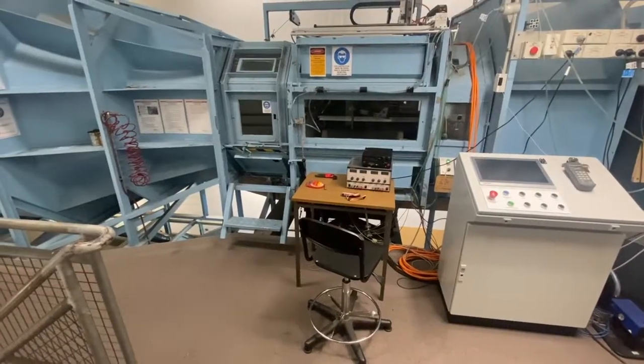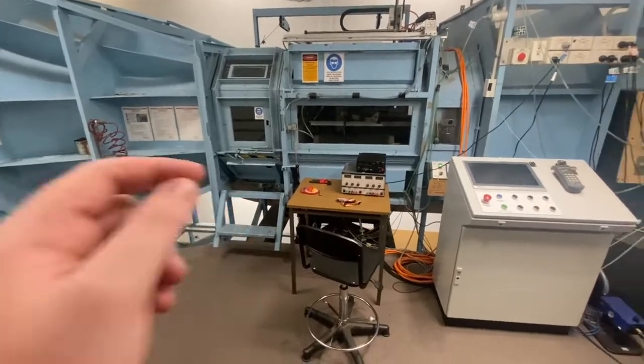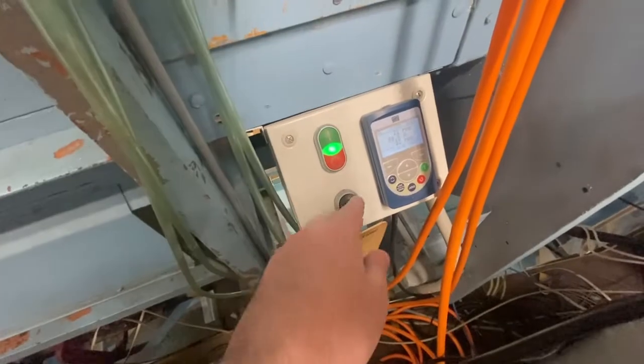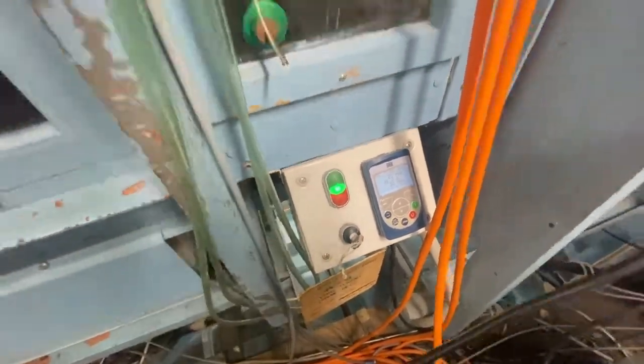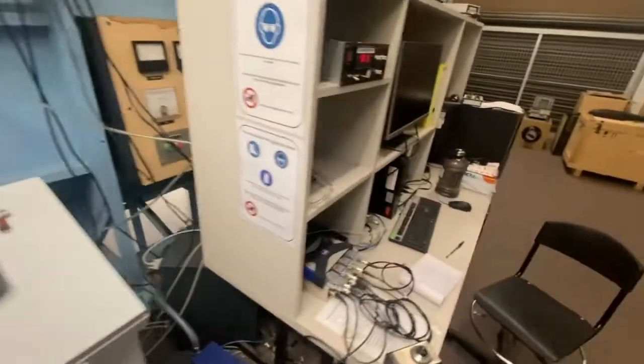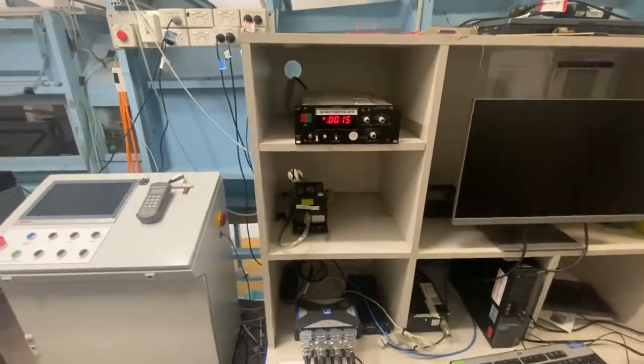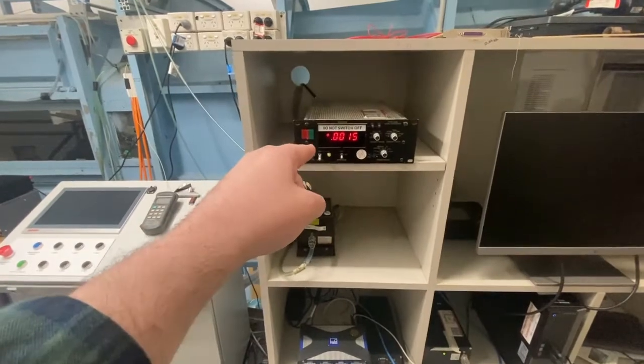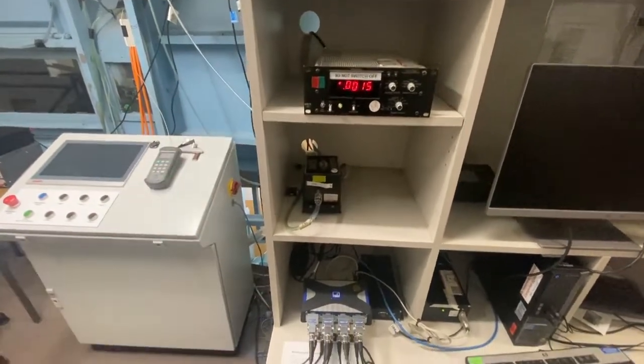So, before operating, we need to ensure that the hatch is securely shut. Next, ensure the key is engaged and the wind tunnel has power. Next, on our right, we need to ensure that the pressure indicator is correct. It should read about 0 kilopascals, and so we should keep an eye on this through the test.